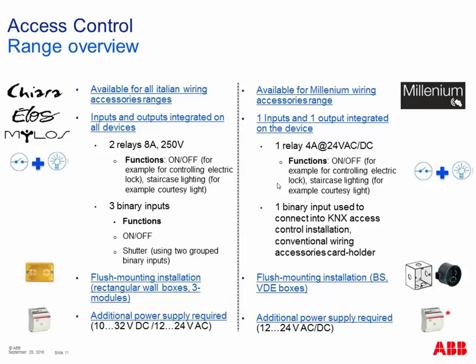This additional power supply grants that the installation is working also if the KNX bus falls down. This is an important security aspect, since this means that if for some reason the KNX bus is not working, the additional power supply grants that the customer, so the guest, can enter the room.